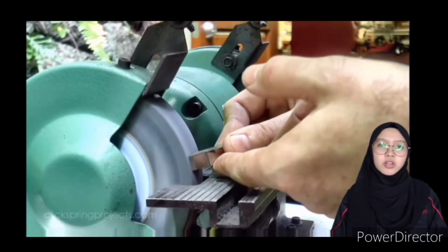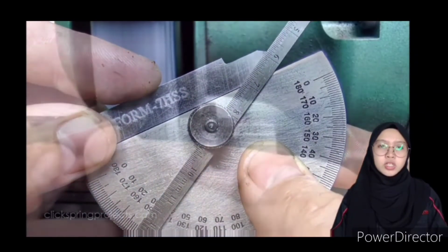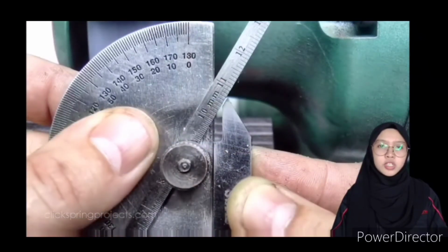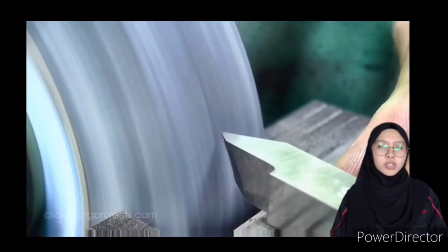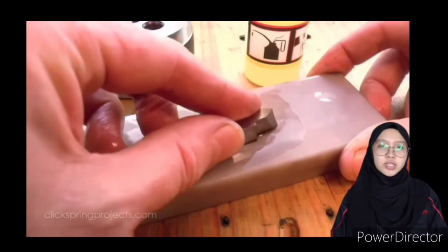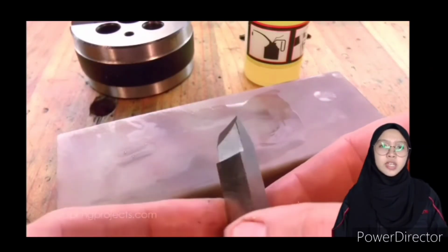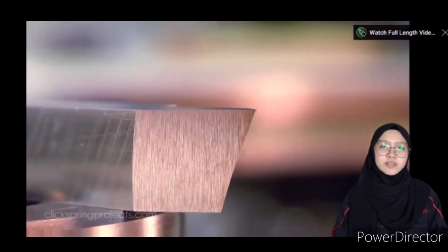Check the amount of end relief when the tool bit is in the tool holder. Then hold the top of the tool bit at about 45 degrees to the axis of the wheel and grind the side about 14 degrees. Last, grind a slight radius on the point of the cutting tool, being sure to maintain the same front and side angle. So next we can proceed to the threading process.